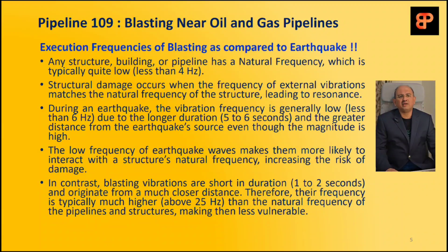So even though magnitude of the earthquake is high, because of the longer distance, the frequency is normally low, below 6 hertz. And the low frequency of earthquakes therefore makes it more likely to resonate with the natural frequency of the buildings and structures or pipelines, and thereby increasing the risk of the damage.